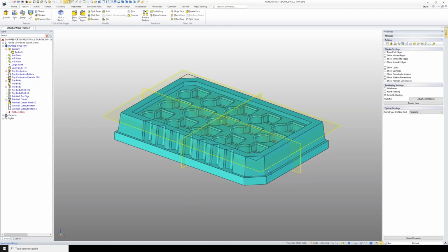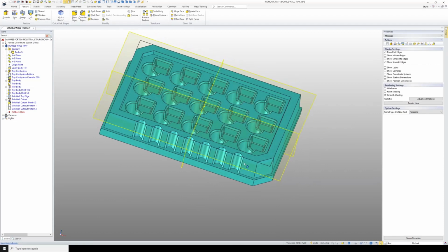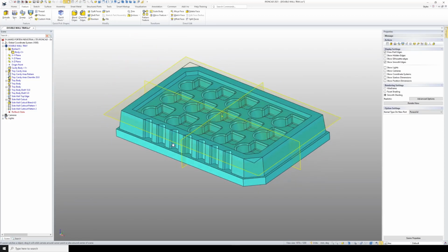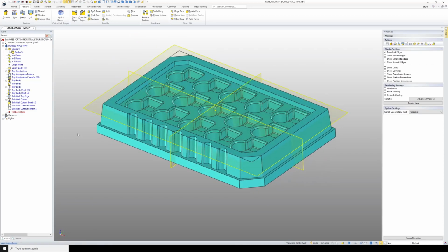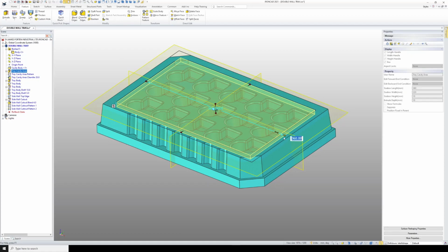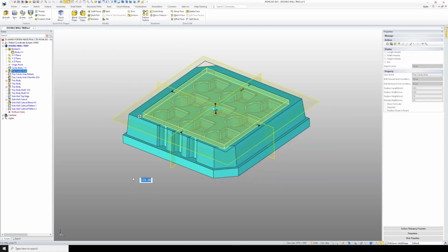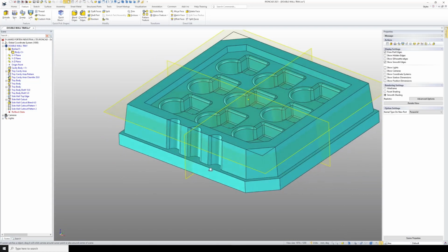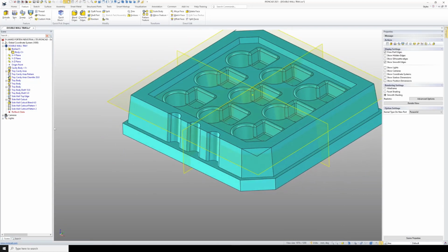It resizes, and IronCAD is going to maintain or recalculate what it can fit in within the constraints that I gave it. So that's the reason for doing it the way we have, because we want our model to have some form of intelligence. And so we'll change this back to 220 again, just so it's not so taxing on the computer, and add the blends that we want.